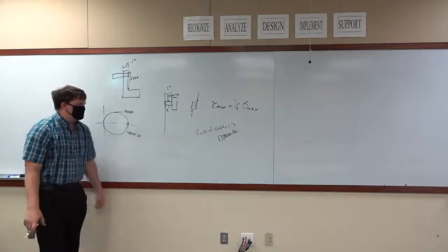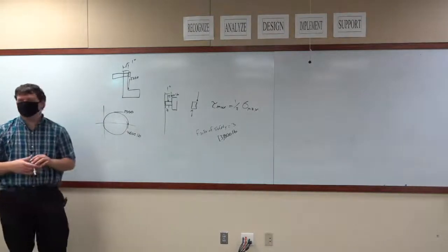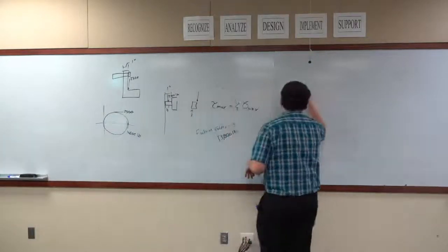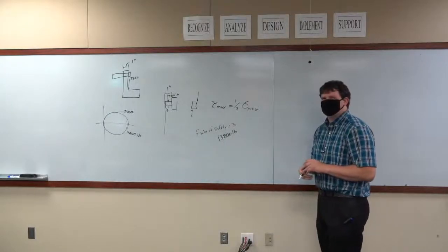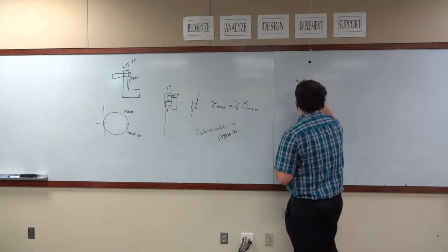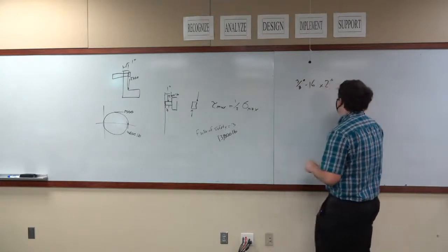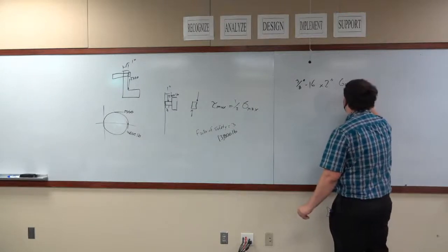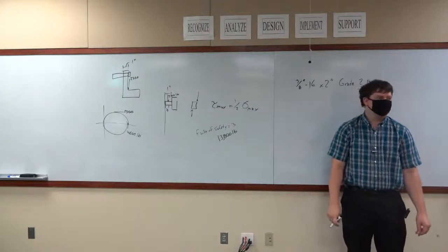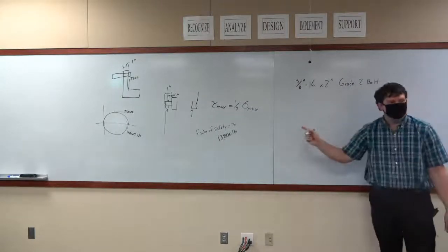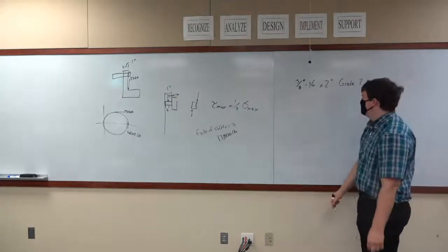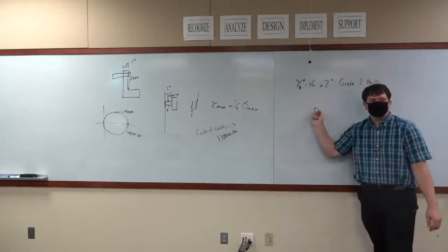Technically, a 1/4 inch bolt can't handle this. A 3/8 inch bolt should be able to handle this, grade 2 3/8 inch bolt. So what you would do is, I think it's a 3/8-16. The bolt specification would be 3/8 inch 16 by 2 inch grade 2 bolt. That's it. There is one answer. Now you pick a 1/2 inch bolt, yes, that's going to work. You pick an inch thick bolt, yes, that's going to work. You pick a 4 inch long bolt, yeah, that's going to work.